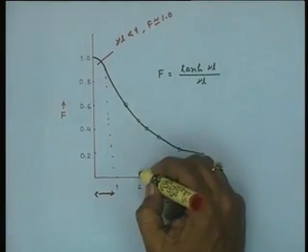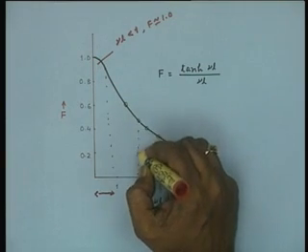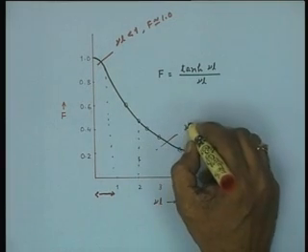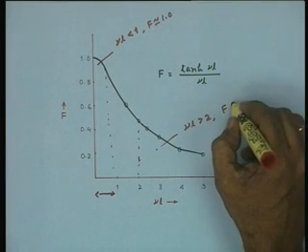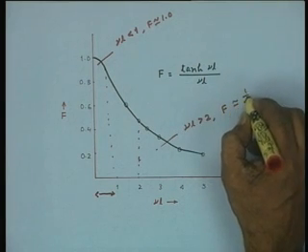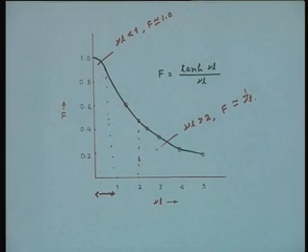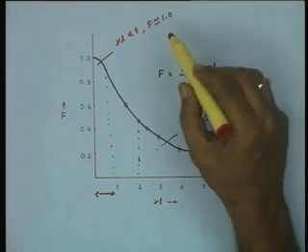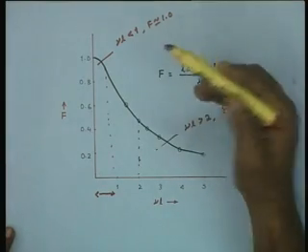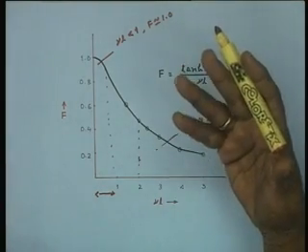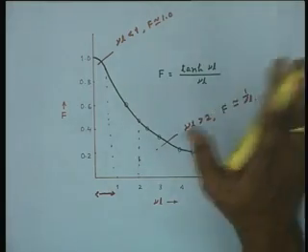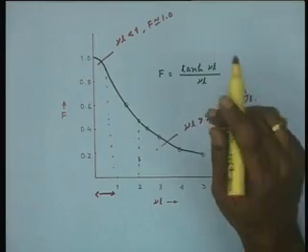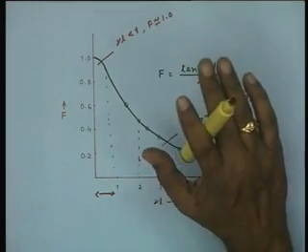On the other hand, when you go to gamma L value greater than 2, f is approximately 1 upon gamma L. So, essentially when we say f is equal to 1, it means that there is no effect on the kinetic parameter Km, or there is no diffusional limitation. In other words, the Km is not altered as a result of mass transfer diffusion.